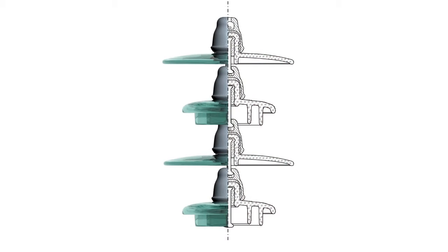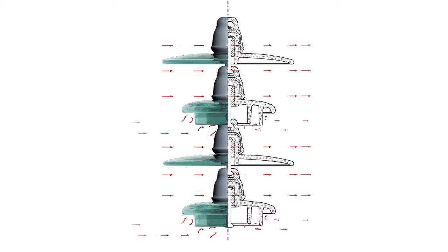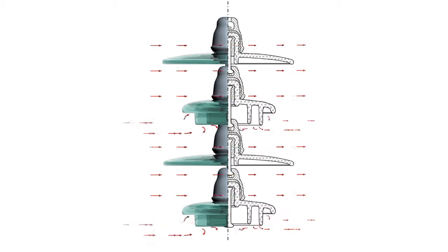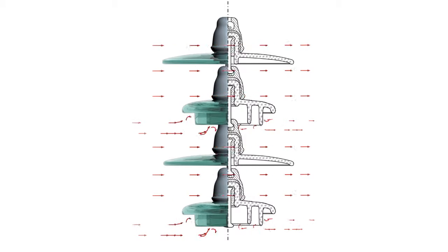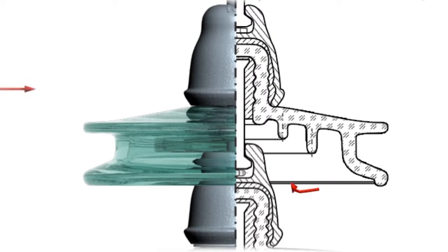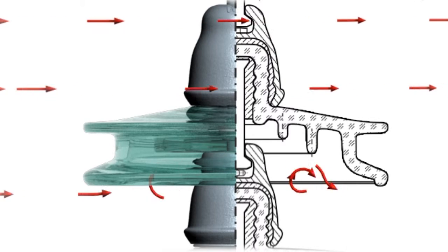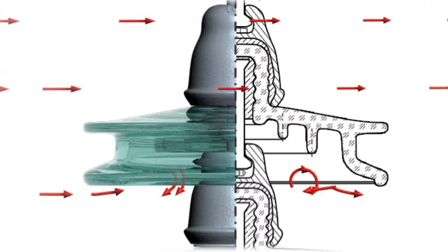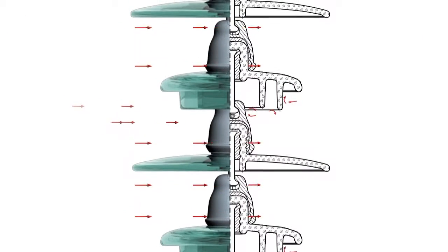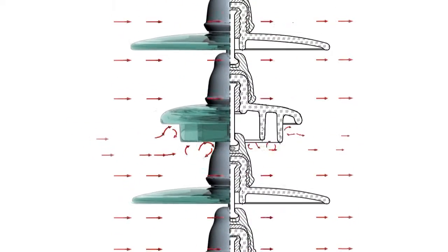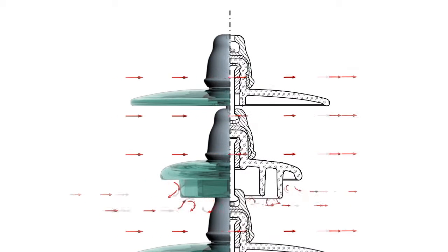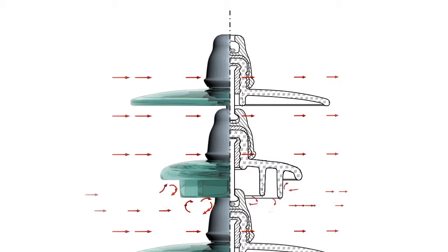When blowing wind current with fine dirt particles, the flat disc of the aerodynamic insulator provides turbulent air curls above and below the surface, and contaminated particles do not settle. It is much more effective than a flat profile of insulators of the PSD type, providing only a one-sided, steady flow. By this method of vertical contamination settling and horizontal turbulent flow, the space between the extended vertical ribs of an insulator type of U70BL are not contaminated.